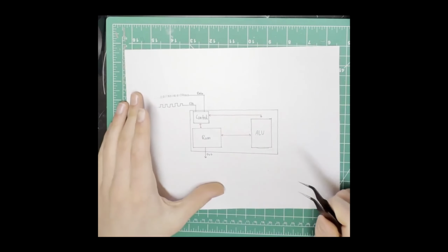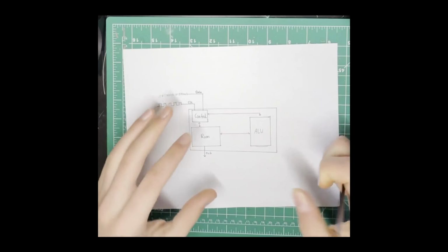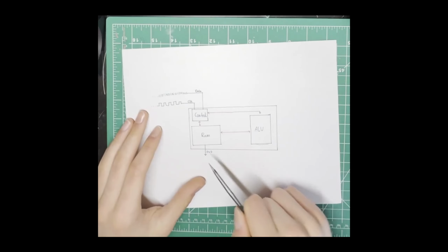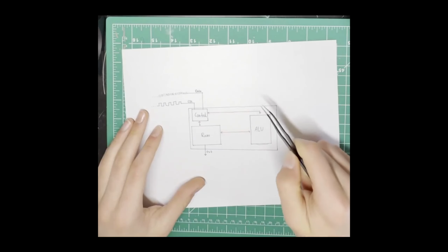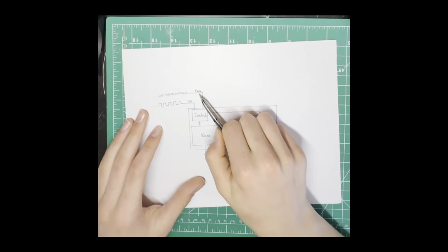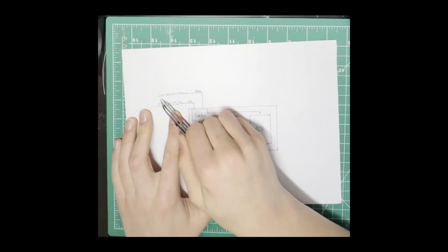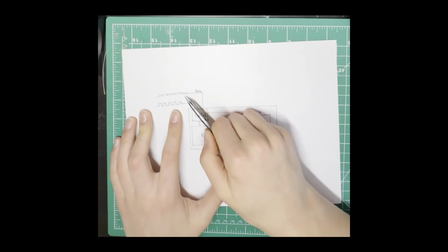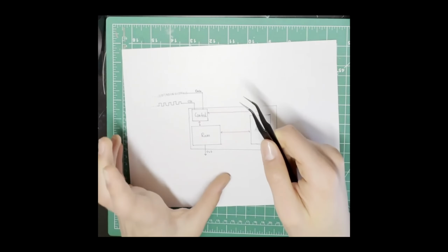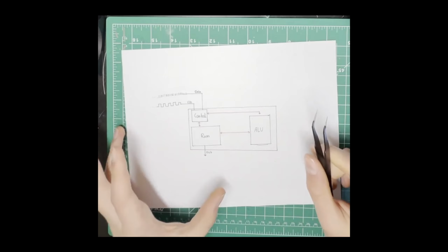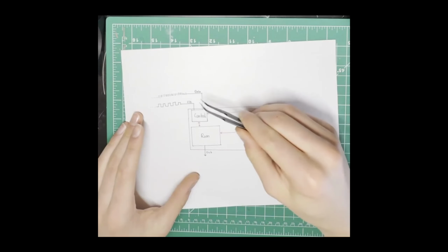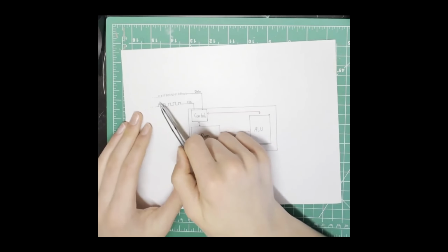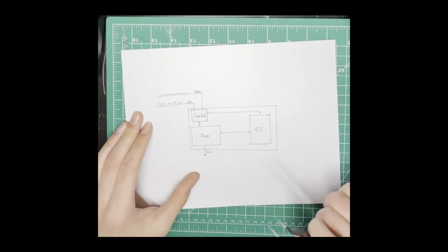Now, this part's the actual CPU, this thing contained inside the box. This thing out here is the input, what actually feeds the CPU what to tell it. So this is the clock and this is the instructions. The instructions do not come in via serial input. As I look here, they actually come in via parallel input. My current design on the breadboard is a 4-bit. So this is a 4-bit parallel input for each clock cycle, not a serial data input. So this looks kind of deceiving, I'm afraid, sorry.